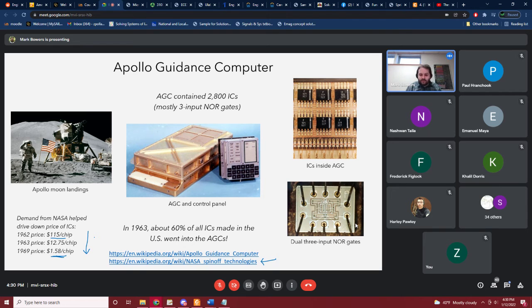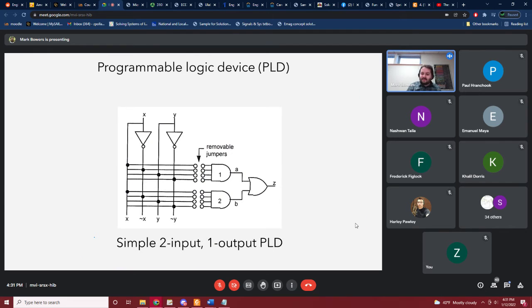right directly in silicon. But there were a lot of places where you're just making 10 of something, or you're just somebody tinkering with stuff, and you want to have a particular logic gate. You can't go and make what's called an ASIC, application-specific integrated circuit, like a processor or like a whole actual chip on your own. You'd have to make it with either a bunch of TTL gates, or they started making devices called programmable logic devices. And what this would be is a real simple example.